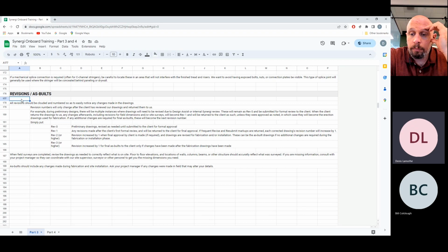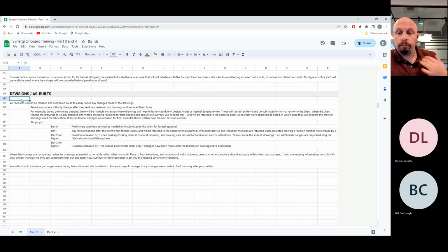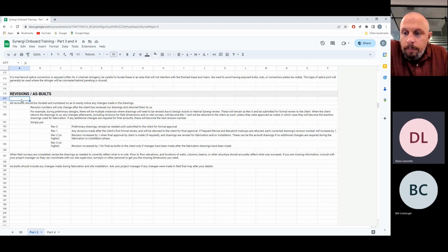It could sometimes be an error when they're building, where the steel erectors, or the guys pouring the concrete, poured too much, or didn't pour enough, or didn't install the steel in the right spot. So floors can sometimes shift around from what was anticipated. But that's unfortunately going to happen, where we're going to have to revise our drawings. Other factors to consider, not just the floor to floor, but we have the opening size in the floor slab. So if our stair dies into the side of an opening, we need to know where that edge is. If there's steel support that we need to tie into, we obviously need to know where that structural steel is, so we can design our plates accordingly.